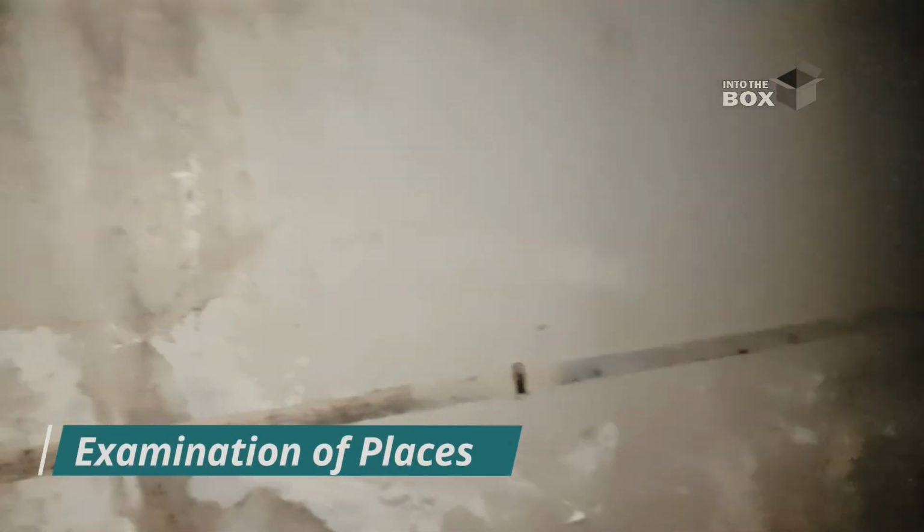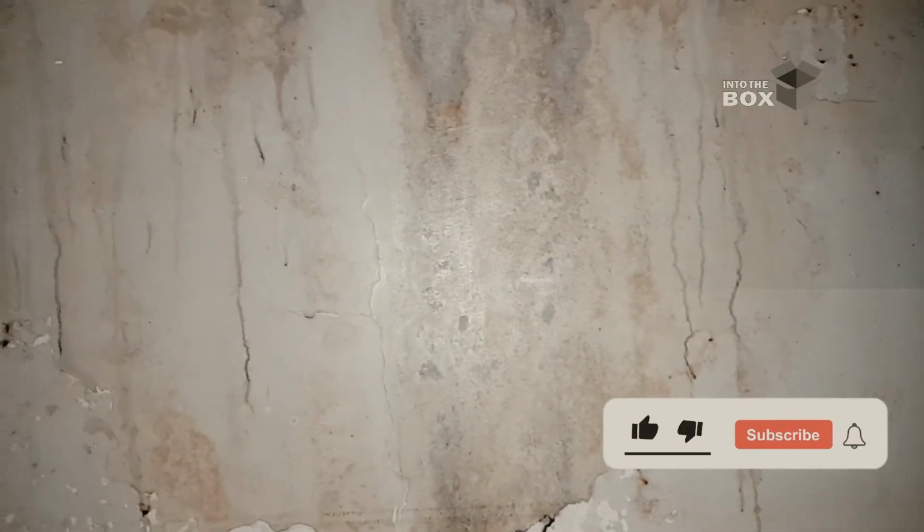With this activity, first of all, let's examine the places where there is any deterioration or any cracks over the trench walls, slab, or the roof. For example, this is the place where we can find some cracks on the wall. These may be superficial cracks, but in visual inspection, obviously, we are looking for all those cracks which are visible on the surfaces. Later on, we will do the detailed analysis through different apparatuses, and we'll inspect the nature of these cracks, whether they are superficial or deeply penetrated into the wall or the slab.